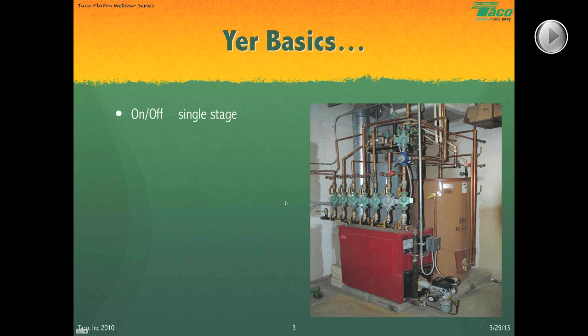if it's a cast iron boiler that needs to maintain temperature for whatever reason, whether it's a really, really large boiler in a light commercial application and you don't want it to turn cold, or whether it's a cast iron boiler with a tankless coil built into it to make domestic hot water, you would have a boiler with a triple acting aquastat. So we're going to talk about both of those, a high limit aquastat and a triple acting aquastat. They're kind of the same thing, only different.